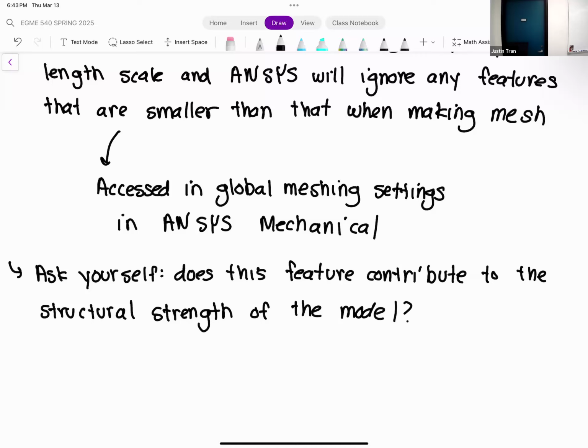Okay, so let's look. How much pressure is on this one? 20 PSI. Deformation. This model is actually not that big. Even though I say it's a bridge, it's not a full scale bridge, it's like a toy bridge. But what I would test is this: the deformation right now is about 0.3. If we double the pressure, the deformation should go up. So that's 60 PSI.